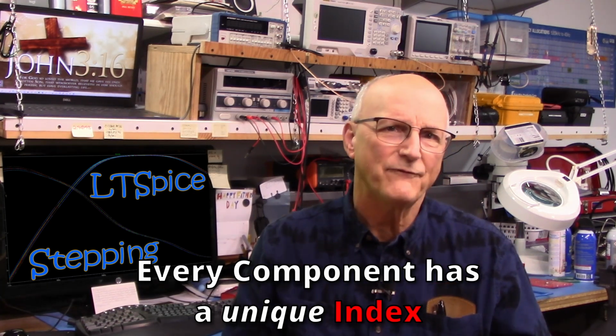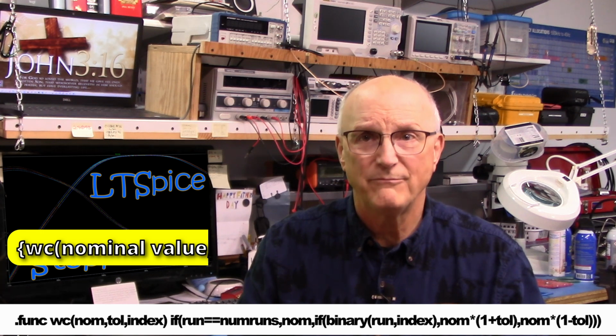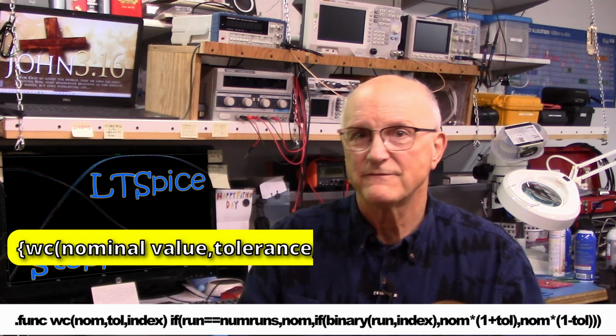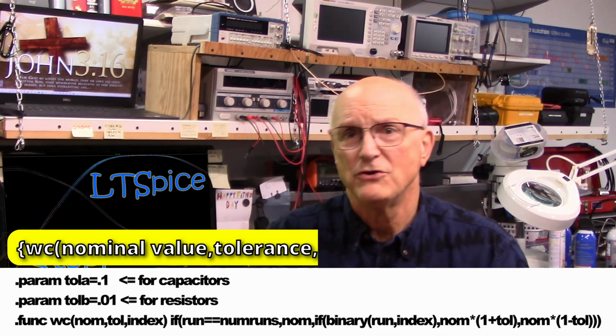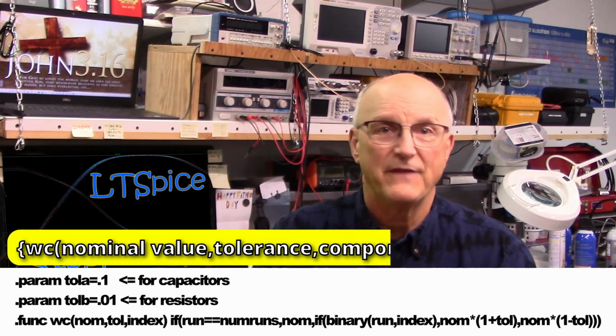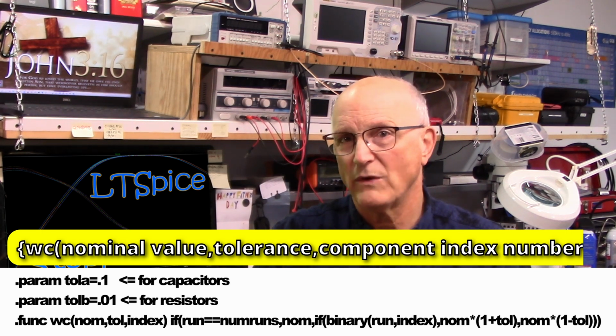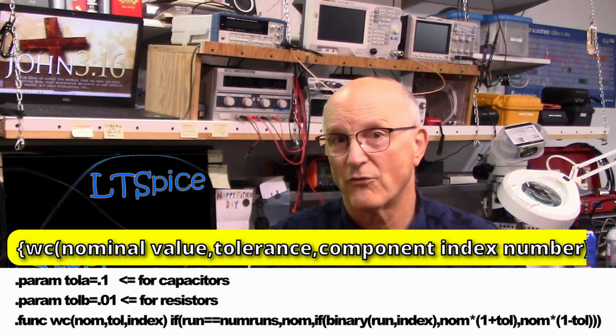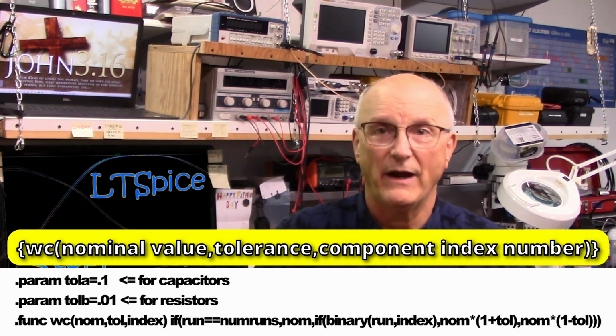The syntax that we have to use is this: left curly bracket, WC, this is the function defined earlier, left parenthesis, followed by the nominal value of the component and a comma. Next is the tolerance, followed by a comma. Now we've defined TOLA and TOLB to use for the tolerances. Then the index number for the component, which is unique to this component. We follow all this with a right parenthesis and then a right curly bracket.